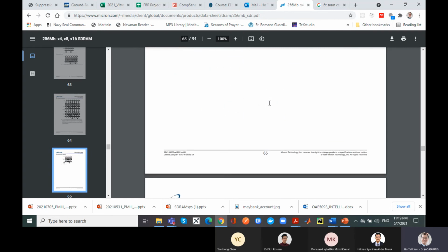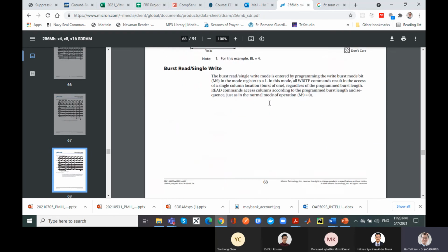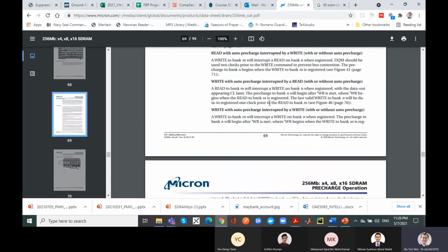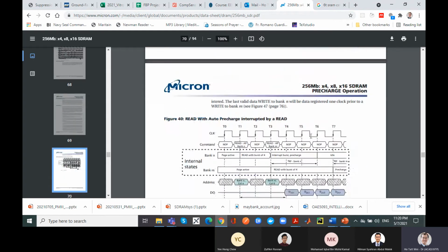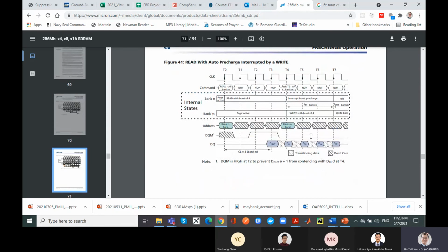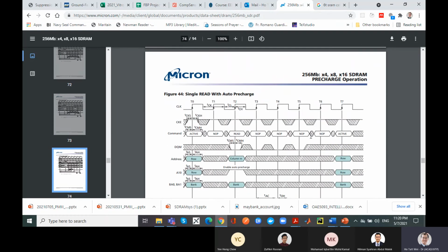And then hopefully by later this Friday, I will cover the FPGA. But I'm a bit handicapped. I'm not able to show you the UCF and all that, but actually it's quite straightforward. As long as you can simulate your design, you can synthesize it, it's already okay. The only extra thing you need to do is specify which input pin goes to which output pin of the FPGA. That's all you need to specify. The rest, if your design is not too complicated, will fit into the FPGA. If it's too complicated, then you have a problem.